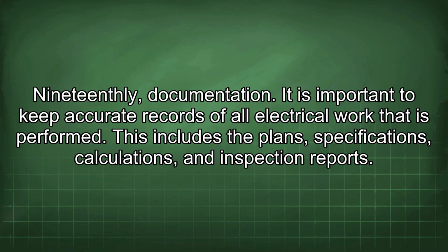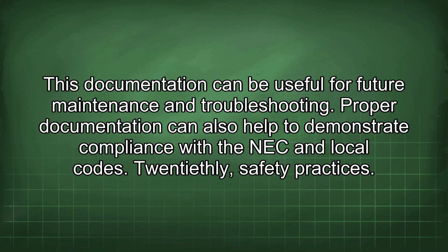19th, documentation. It is important to keep accurate records of all electrical work that is performed. This includes the plans, specifications, calculations, and inspection reports. This documentation can be useful for future maintenance and troubleshooting. Proper documentation can also help to demonstrate compliance with the NEC and local codes.